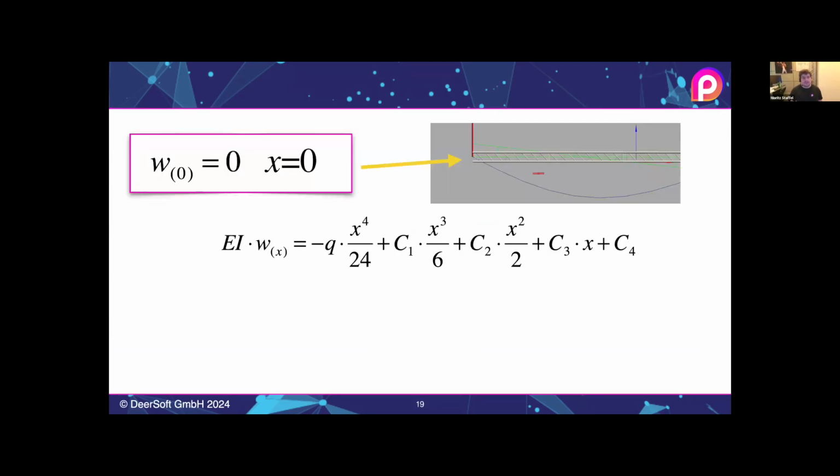If the deflection at the point 0 is not 0, so if the truss is not leveled, it does not come out with the same equation. So the important part to understand with all calculations with 3 or more hoists for truss lines, or 4 and more hoists for any frame structure, is that the actual result of the calculation depends on the assumptions that you make upfront.